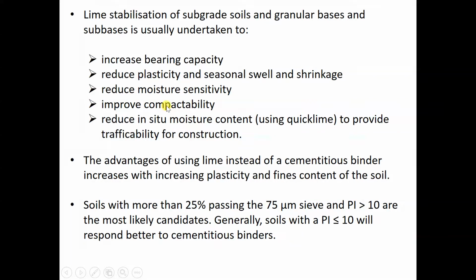Lime is not so much for strength compared to the cement or the bitumen. But especially after you stabilize the subgrade with lime, it will be easier to compact because the soil maybe initially was quite weak, quite soft. After you stabilize with lime, it will be a bit harder and easier to compact.